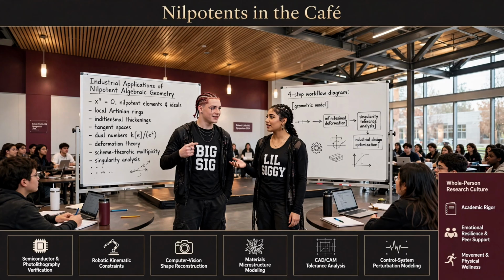Ignore the wheels completely. Ignore the physics. Just calculate a smooth, collision-free line through the factory. That impossible, purely geometric path is the Ariadne thread. But the robot can't actually drive that thread, because the thread might require the trailers to slide sideways like crabs to get around a tight corner. It is a non-admissible path.